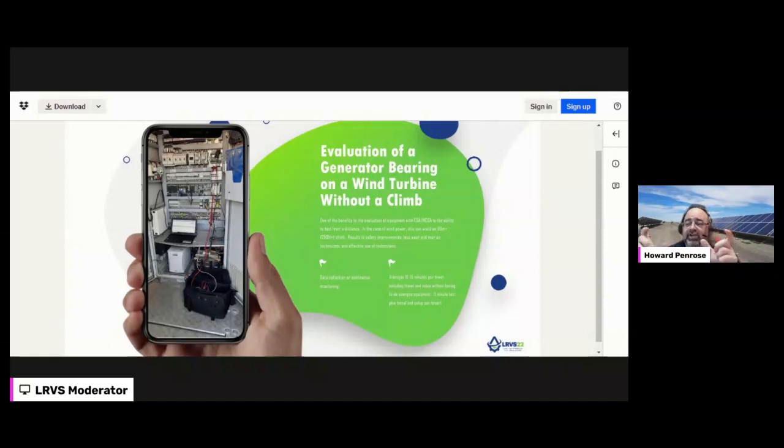And the double roller ones, when we see an outer race signature, that generally means they haven't been lubricated properly. That's the number one thing with those that leads to their failure. And one of those failures equates to 800 thousand to 1.2 million US dollars. So it's a significant impact, let alone the months that the tower is out of commission.